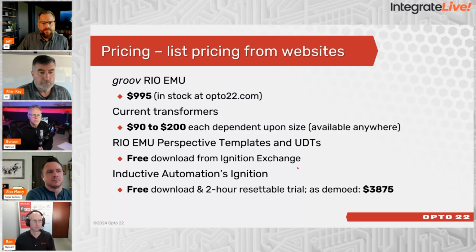And power factor is important, certainly from that aspect, but power factor also tells you how much energy you're paying for. So the utility has to provide you this energy. Now, how efficiently you use that energy is up to you. So power factor gives you that kind of visibility in how efficiently you're using it. So this isn't perfect math, but essentially if you're getting a power factor of 0.7, or 70, or however you want to calculate it, it's usually a value of 0 to 1. So it's 70% essentially. That means 30% of your power is essentially being wasted.